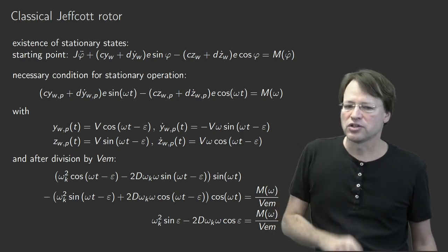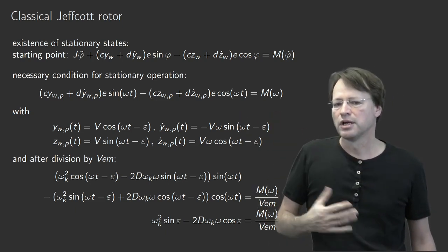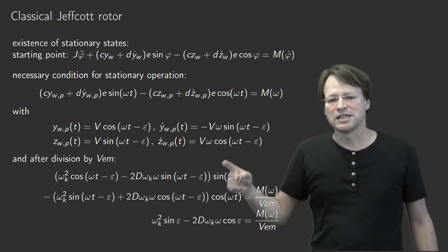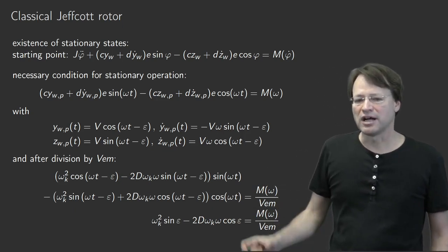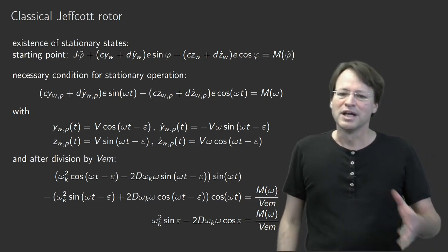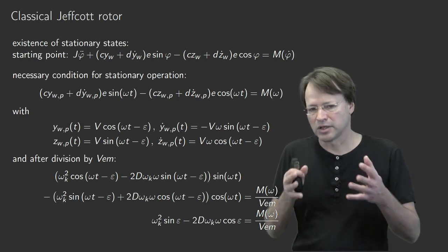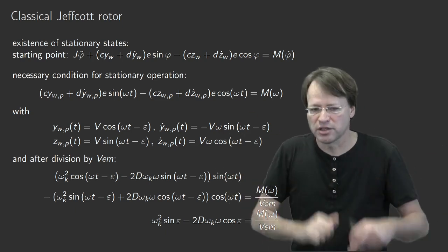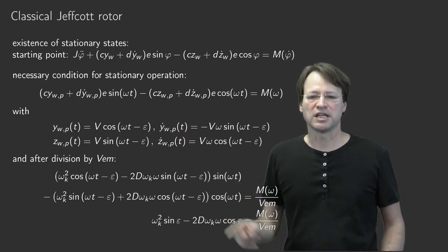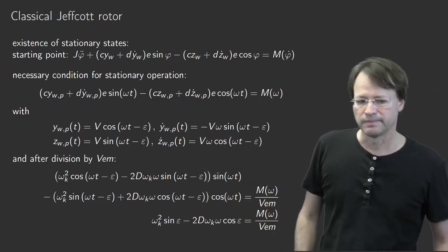And for the equation for the driving torque, we just have to assume some characteristic curves which come from the driving mechanism, for example, an engine or whatsoever. But for the system torque, I would like to derive a nice expression, nice but still complicated, I'm sorry for that, as a function of omega, and we will draw these two characteristic curves, and their intersection marks the state of balance and marks a possible stationary state. A necessary condition, not a sufficient condition. We will discuss sufficiency issues later on.